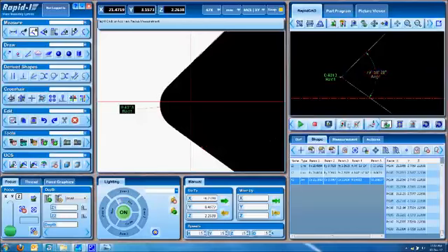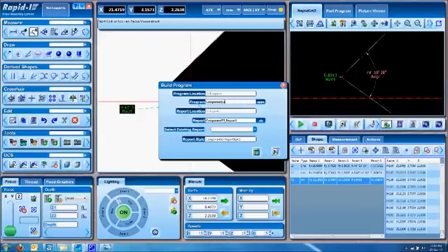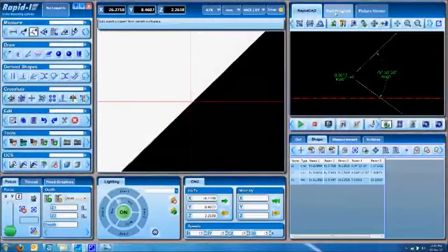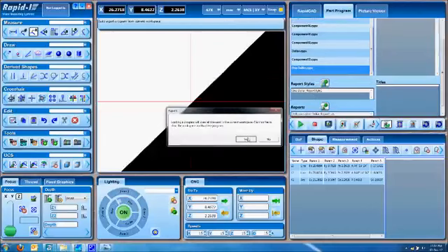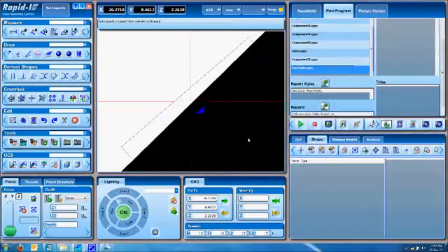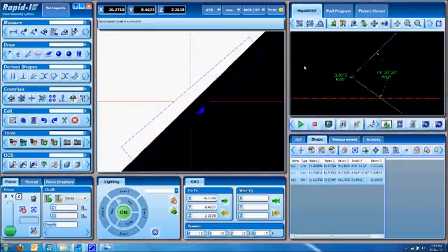The software has been recording every step we have been doing. So click on Build, give a name to the program that you would like, and then just click on Build. It makes a part program for you. To do repetitive measurements, we can go and recall the part program. Go to the home position of the component, switch on the CNC mode, and click on Run.